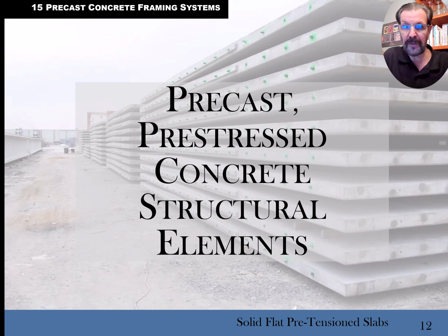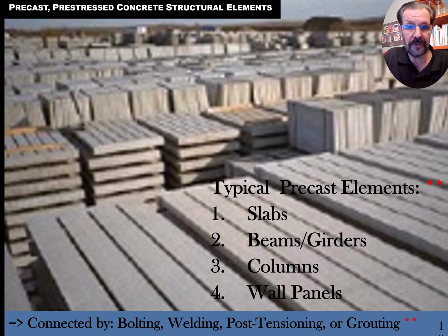In this background picture, you're seeing solid flat pretensioned slabs. Most of these parts are going to be precast but prestressed, and mostly it's the pretensioned variety of prestressed as opposed to post-tensioned. But there are exceptions. So let's look at this list here.